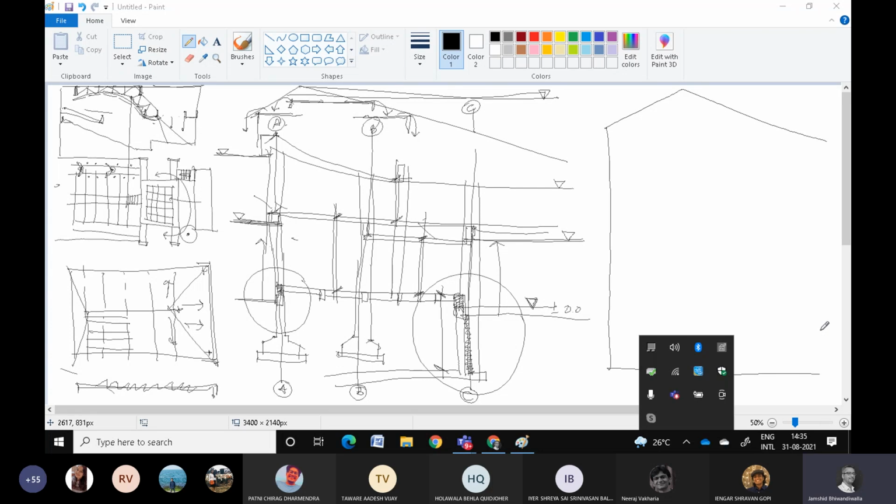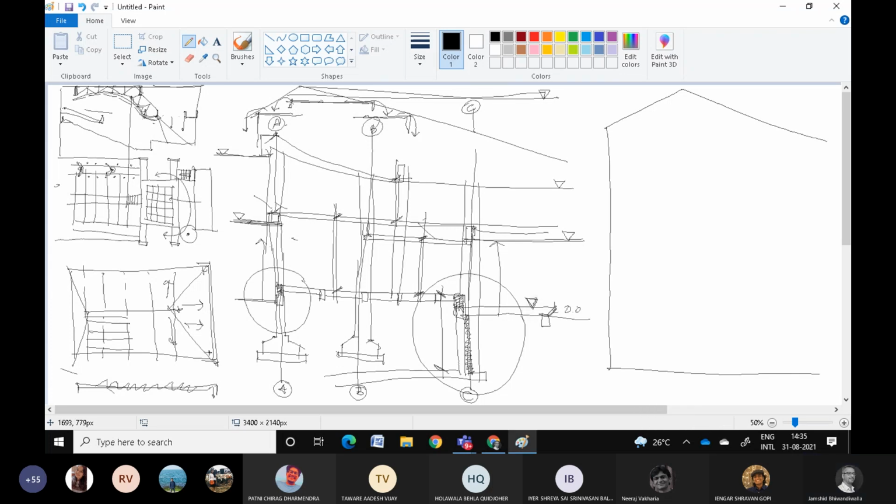Like you see a beam here. Suppose a plinth beam is put in here. However, you just show that this is a line without any reference, and do not show the footing part of it. Sometimes it looks odd. Though the column and the footing may actually be in elevation and you are actually cutting through the plinth beam, sometimes it becomes necessary to show certain things in elevation.